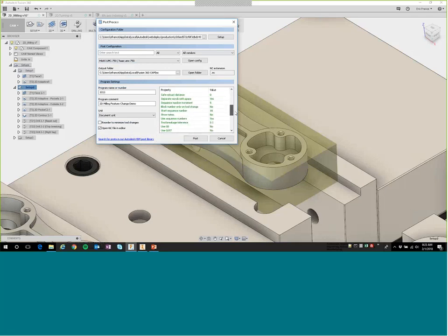There are some things that we can actually go through and set up, like if we wanted to use G0, or use G28 to G53, we have the ability to set those up in the operation itself instead of having to integrate those in the post processor, especially if there's something we're going to be doing on an arbitrary basis.